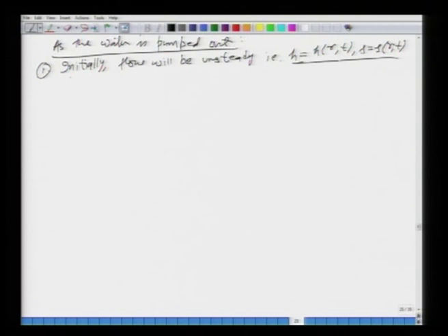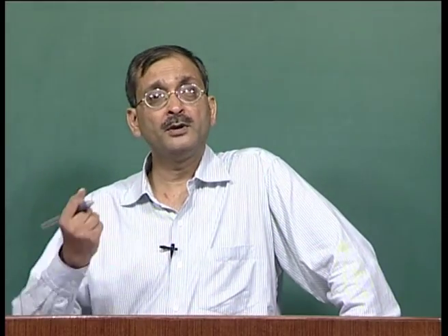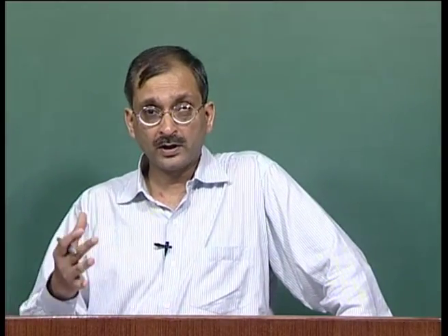And another important thing to note is that the pumped water comes out from the storage in the aquifer, unconfined we are talking about. So, initially when things are unsteady, where is the water coming from? It is coming from the storage which is there in the unconfined aquifer.